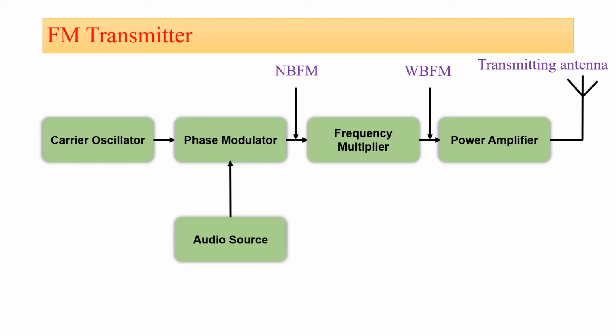In the block diagram the crystal oscillator is used which will generate the stable carrier signal, and the modulating signal and the carrier signal are applied to the phase modulator to generate the narrow band frequency modulated waveform, that is NBFM, narrow band frequency modulation.